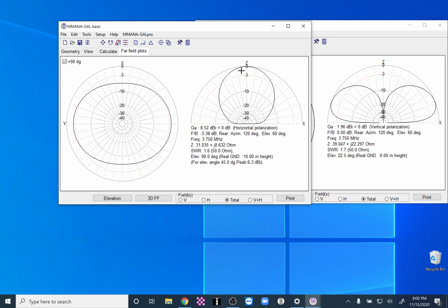Just have to slice. So here we have our NVIS antenna, 80-meter dipole, 10 meters off the ground, horizontal, versus a quarter wave high, 80-meter vertical with 8 ground radials, and we have our radiation pattern at low angle. Obviously, these two antennas are not going to be talking to each other.